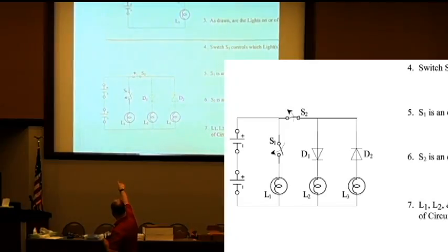So the plus is closest to the plus on D1. So that diode will work. In the other case, the diode plus there goes to the negative side of D2, and as I showed you when you hooked up the batteries wrong on the diodes, they won't light up. So this is where he brought up the point: even though S2 looks like it controls that light, it will never come on because someone hooked the diode up backwards, okay?